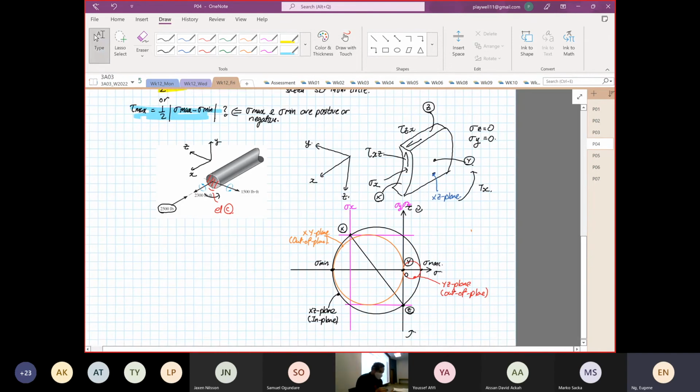So now from here, where do we go from here? We have to determine stress max and stress min. And we know that the in-plane one is the important one. Okay, the out-of-plane one, the inner circles one, they are not critical. Okay. So if the in-plane one is the most critical one, we can just apply what? We can just from here apply the 2D Mohr circle, right? Okay, right? We just need to find the XY plane one.